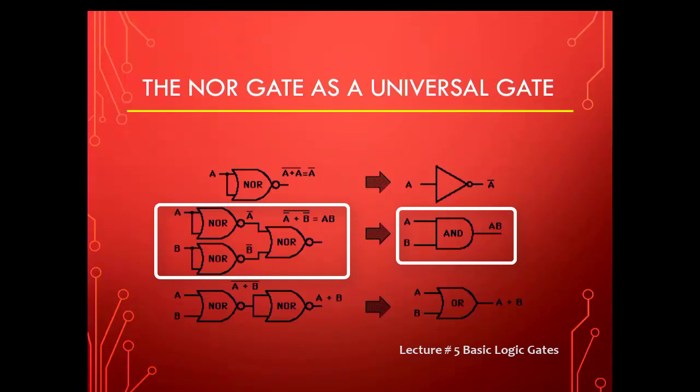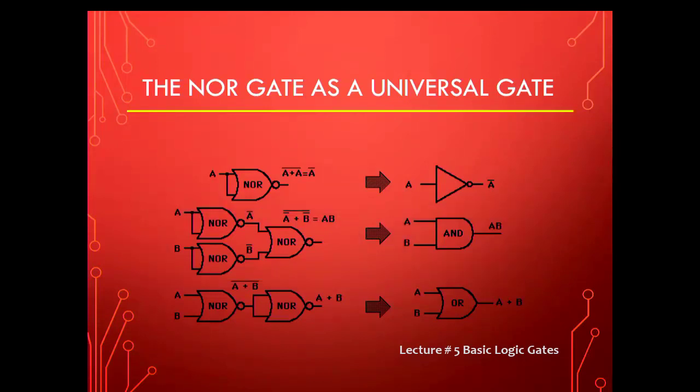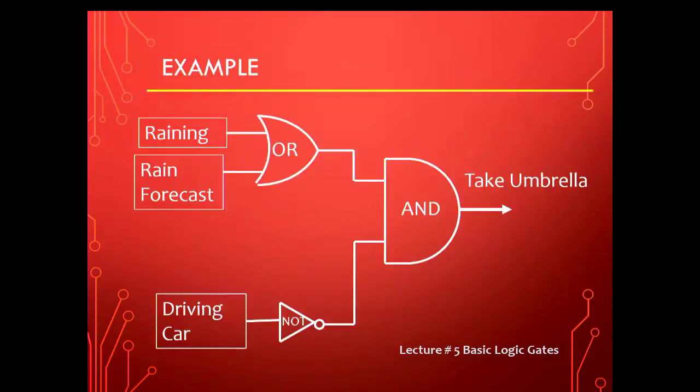So in homework or in the exam, I might ask you, hey, we have a circuit which contains inverter and AND gate. We don't have those, but we still want to fabricate a device using NAND gates or NOR gates. How would you do it, right? So wherever you would have AND gates in your circuit, you will replace that with this whole thing right here. Okay, make sense? We'll do many examples of this. Don't worry about that.